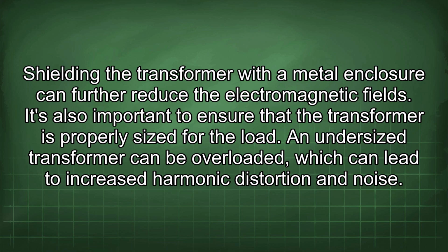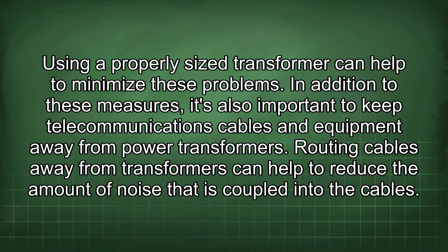It's also important to ensure that the transformer is properly sized for the load. An undersized transformer can be overloaded, which can lead to increased harmonic distortion and noise. Using a properly sized transformer can help to minimize these problems.